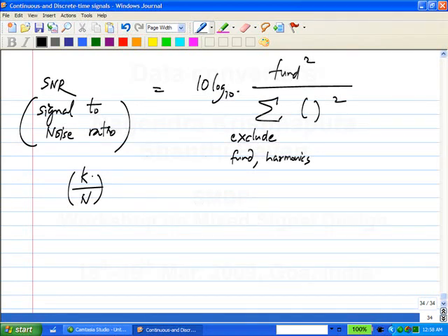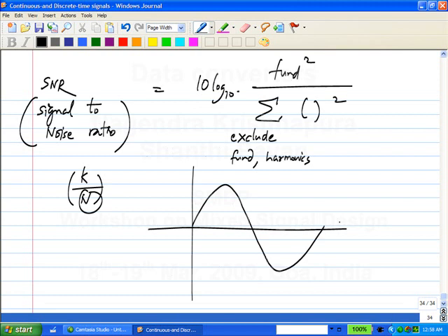Let's say you have a sinusoid and you sample it only at 4 points, here, here, here and here. This is one possibility, and another possibility is here, here, here and here. So the signals are very different now. But when you have a large number, this is not going to happen. You will get points everywhere, whether you take the phase to be slightly different or not. So that's why phase is not a very important thing, as long as you have a reasonably large n.